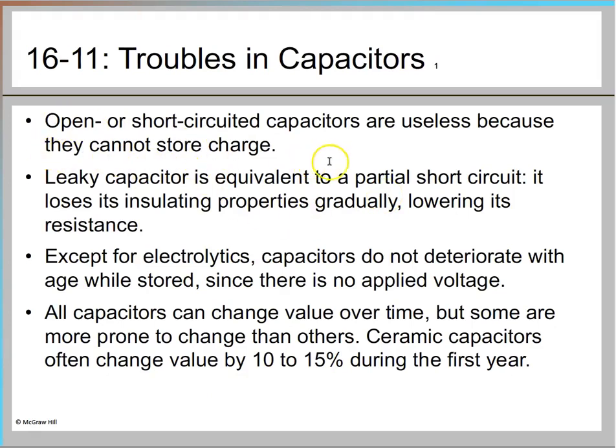Open or short-circuited capacitors are useless because they cannot store charge. Imagine your capacitor is connected in a circuit, and if there is an open circuit, then the capacitor will not be able to charge because there is an open before the capacitor is connected. And if there is a short, so let's say a lead is connected across the capacitor, then all the current will pass through the short circuit wire